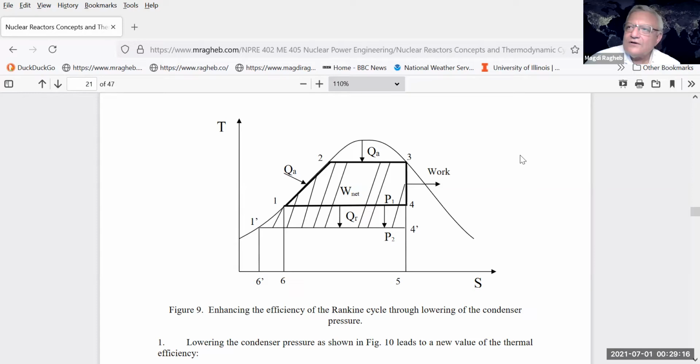It also depends on the weather conditions: our engines in that case would operate at a higher efficiency. You get a higher rectangle here in the winter than in the summer, where the rejection temperature is lower. So enhancing the efficiency depends really on the location, or on the season, when it comes to decreasing the rejection temperature.